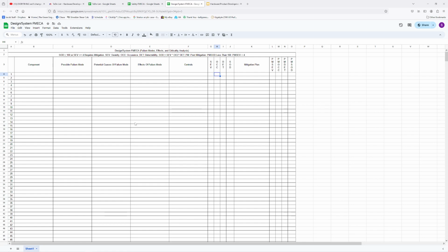So that means on your design FMEA, severity is like a 10. This occurrence is like a 10, and so the severity, machine doesn't work. This is a 10. 10 times 10, that's 100. You already need a mitigation, right? Already, and if you need a mitigation, your product has a problem. Just one.